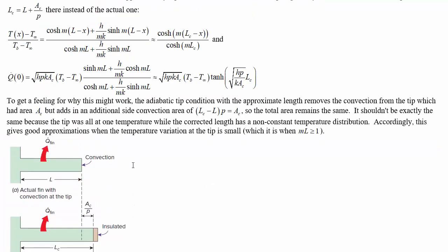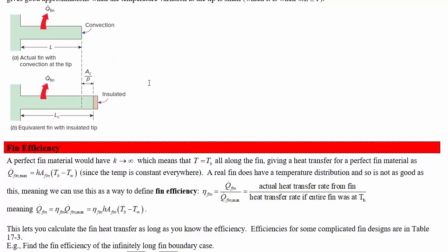But what we found out from the differential equation is that we don't have quite that much heat dissipation as the surface area of the fin times the difference in temperature between the base and the fluid times the convection coefficient, because the temperature at the surface of the fin is decreasing along the length of the fin, since the situation that leads to lots of aspect ratio, lots of area, also leads to generally narrow fins that kind of limit conduction.